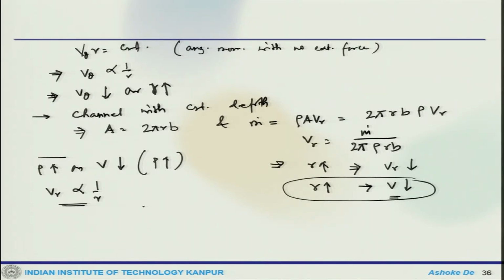So, now if V r and V theta at the leading edge of the diffuser vanes are calculated, the vane angle can also be estimated from the conservation of angular momentum. How? Let us see. So, V theta 2 and r 2 would be V theta 3 and r 3. So, V theta 2 is the tangential velocity at the impeller blade tip. So, already we can obtain that V theta 2 will be U 2, which is r 2 omega.